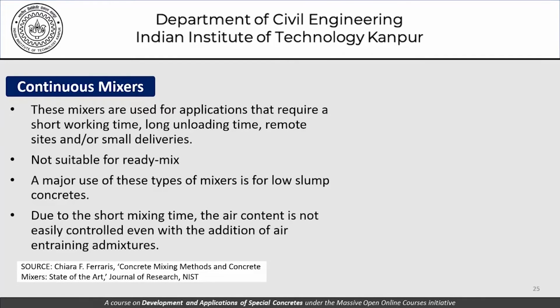Due to the short mixing time, the air content is not easily controlled, even with the addition of air entraining admixtures. So, use of continuous mixers is rather limited in its scope, as we can see from the brief description that has been given here.